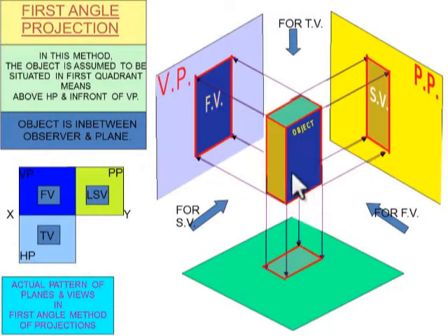So what is a front view? Here FV stands for front view. Front view is nothing but projecting the object. Here this is the 3-dimensional object. It is projected to the vertical plane. If the object is projected to the vertical plane in first angle projection, you get a view that is known as the front view. That is the image of this object obtained in the vertical plane.